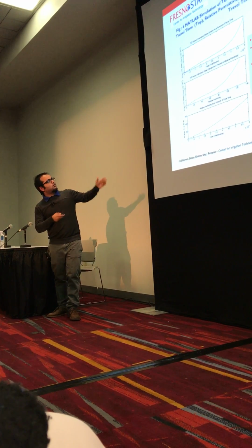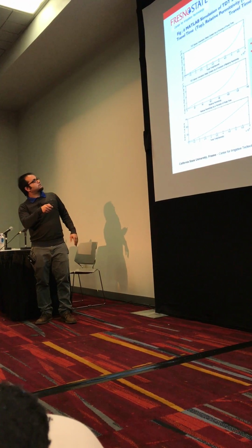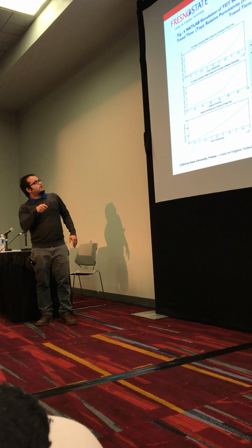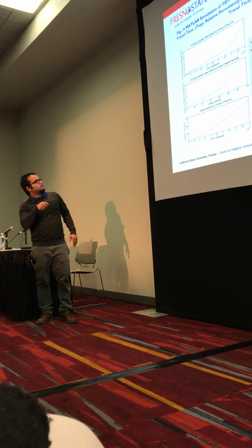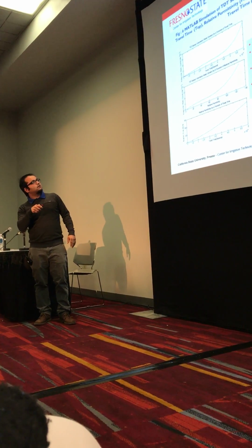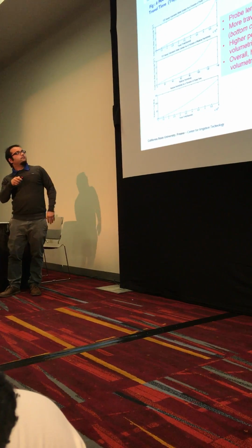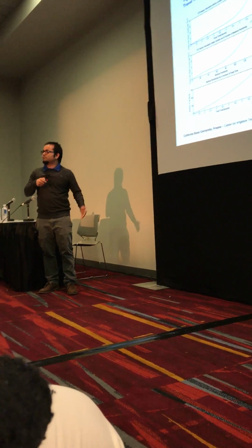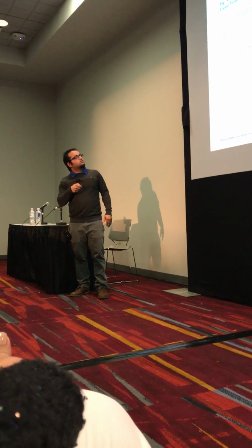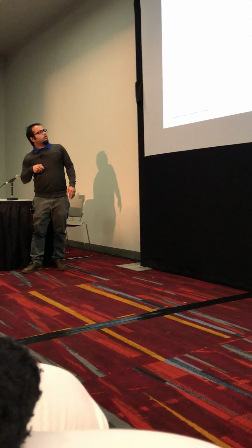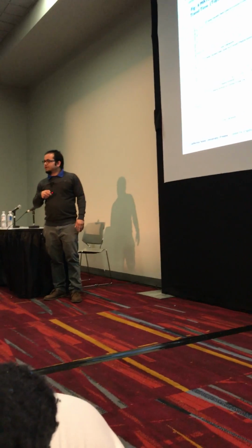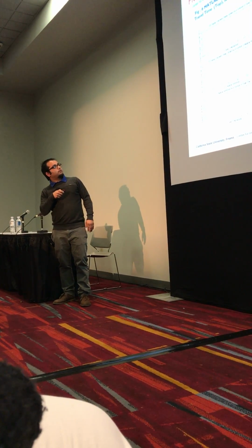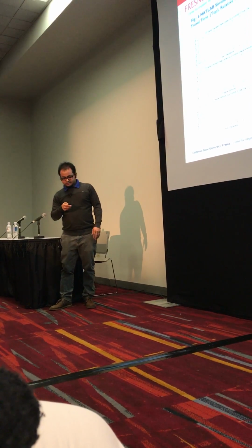I'll go a little bit slow for this one. On the axis you see travel time in seconds and volumetric water content. So if the travel time for one sensor is longer, then definitely that represents more presence of moisture in the soil. So this is how it behaves. More travel time also represents a higher apparent permittivity, or relative permittivity, and that ultimately results in higher soil water content.